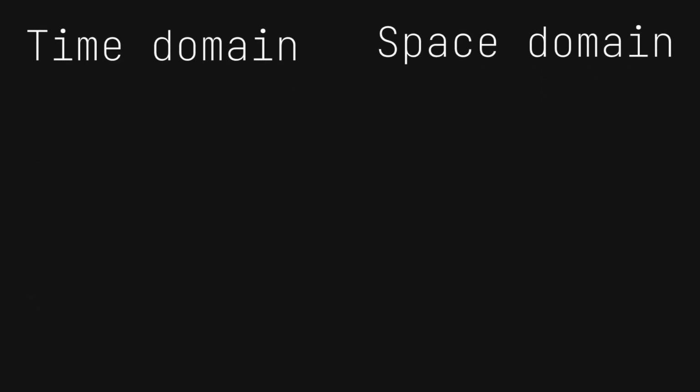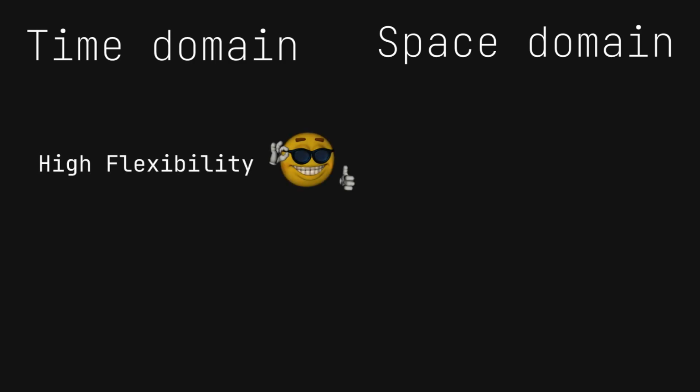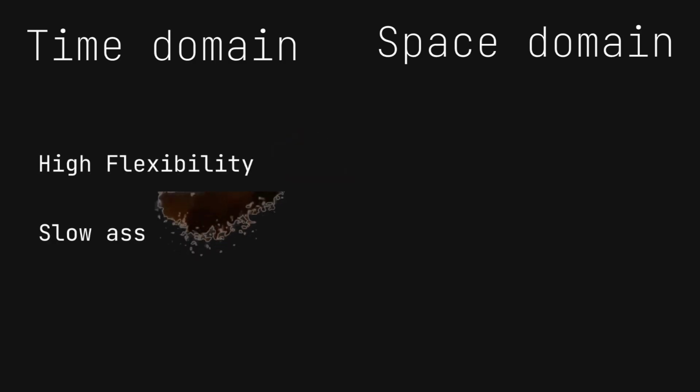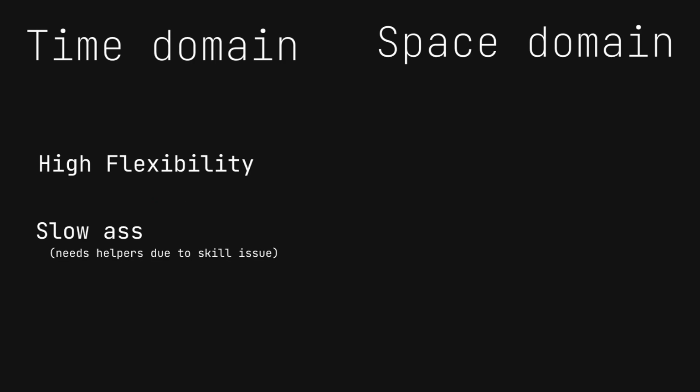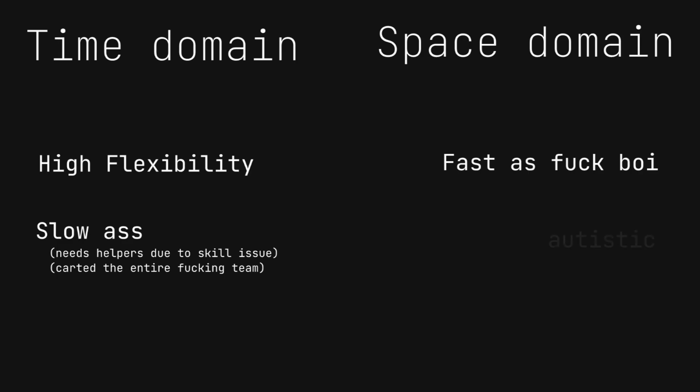The constant reconfiguring of the processor allows it to execute any random list of instructions you give it, but it isn't really very fast. In fact, processors are really slow. We think the ones we have today are fast just because we have increased their clock speed to as much as physics would allow us, gave them some accelerators to help them in specific uses, and spent decades optimizing them. FPGAs, on the other hand, are way more performant due to their massive parallelism. Their flexibility, on the other hand, isn't so great.